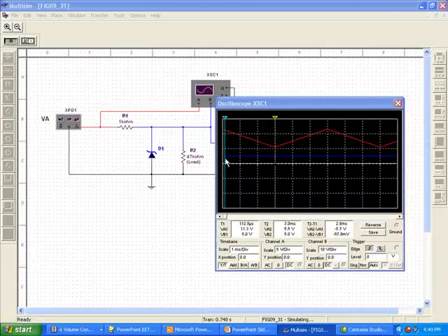If we go here to our highest point, we're going to see that we're at about 11.5 volts. And then our blue line here is at about 5 volts. And just as a frame of reference, if we scroll this over all the way over here, you'll see we're looking at time 1 and time 2, and they're both showing the 11.5 and the 5.